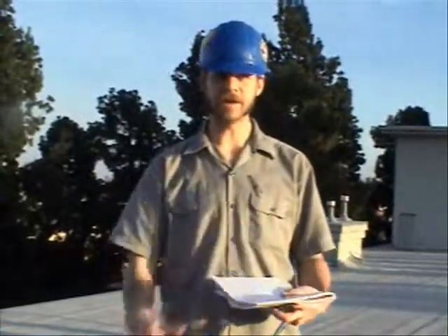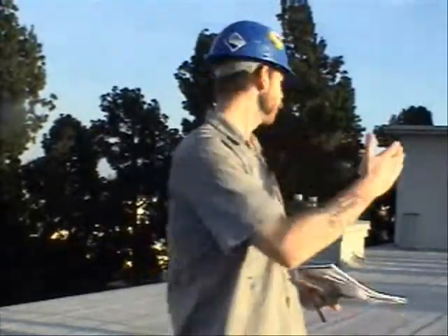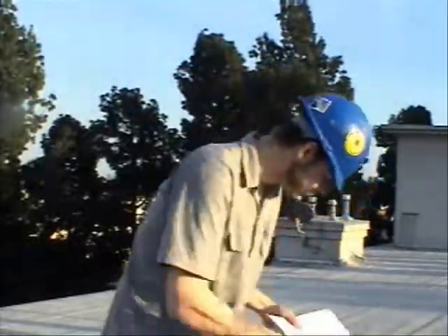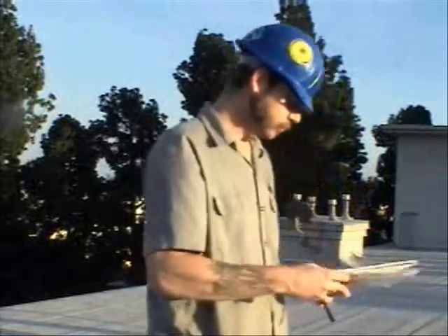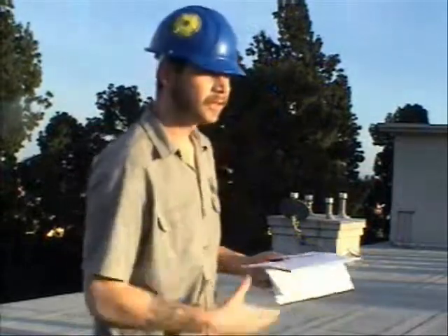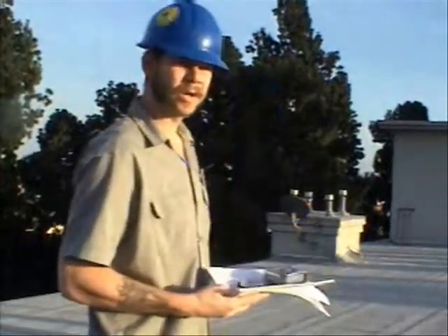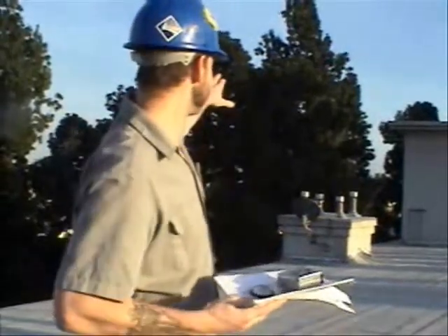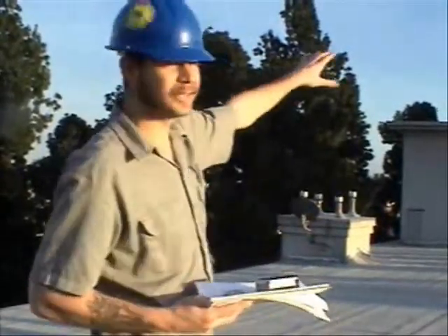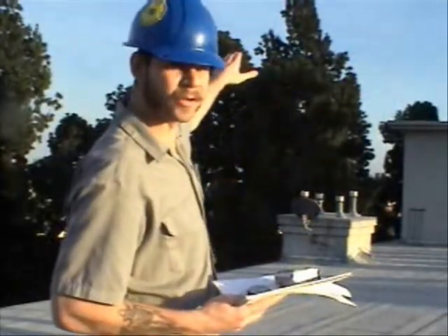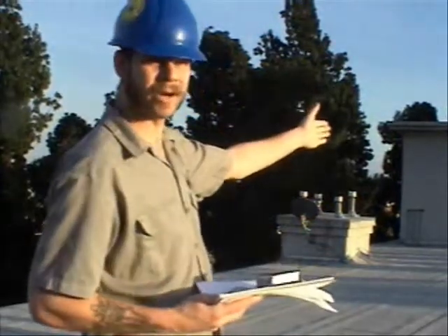The next step after you've made a site layout drawing is you're going to want to measure. You're going to want to take your compasses, and you're going to want to find the places where there's going to be shading. Now, right here at this site, you can see up to the south we have some really tall pine trees. What we're going to do is measure the angle of those from vertical, and find the angle they are from true south.